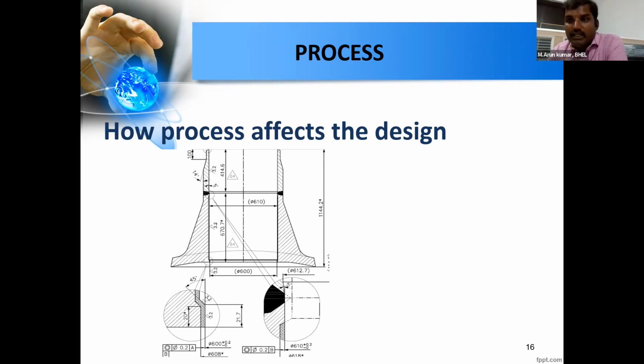There, the material is in between the ferritic and austenitic. So the weld cracks in that region, since austenitic stainless steel weld doesn't require any post-weld heat treatment as per code. After this welding, we are not going for any heat treatment. So whenever we tested in the PQT, we were getting some cracks or some indications in some of the regions.